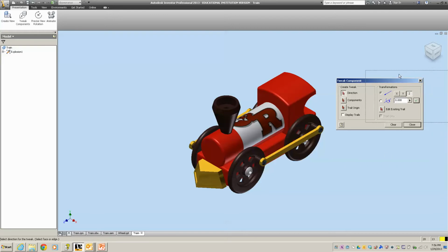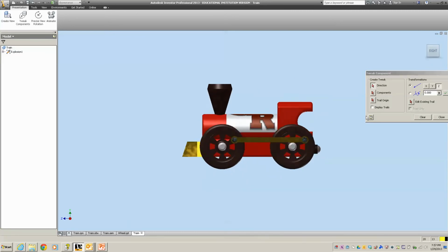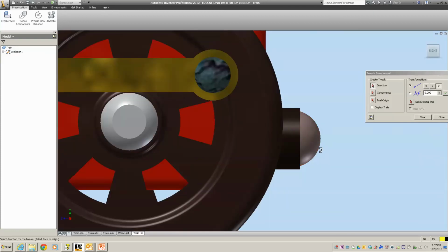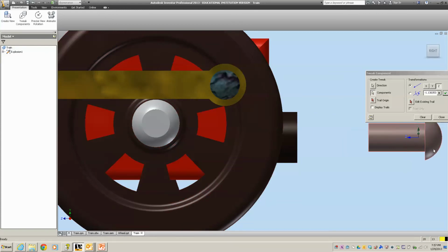So how I'm going to do this is I'm going to first of all start with the right view, and I'm going to pull apart the hitch magnet. So I'm going to zoom on in really close where I can see it. And that's one of the secrets, do not be afraid of using your zoom key. And I'm going to click on the hitch peg. And when you look at this right here, do you see how the Z-axis is in the direction I want to move? And right here, Z is clicked, so I'm in good shape. I just click and it pulls in that direction.